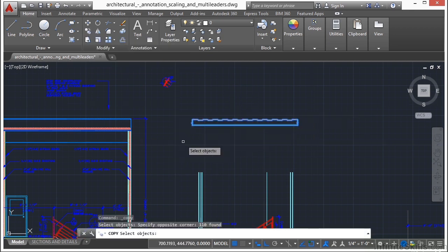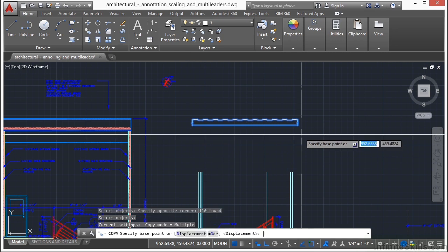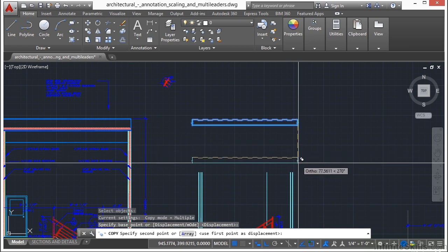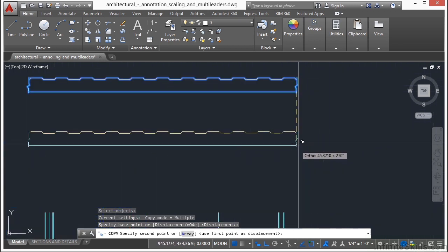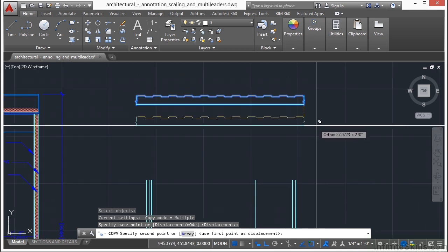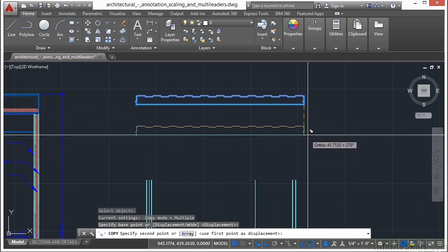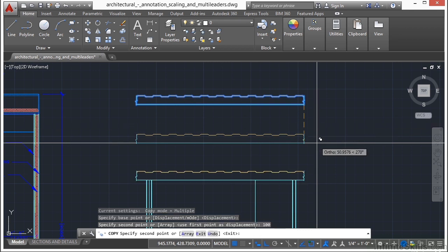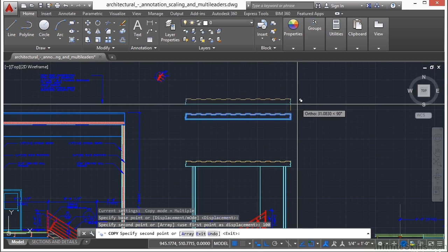Then you select your objects, just like you would in the Move command. Press Return, pick a point on there, and then move it. Now, when you execute the copy command, you can see in the top right-hand corner of my crosshairs is a little glyph. That's telling you that you're using the copy command. So if you forget what command you're in, that's there. So just like with the Move command, I can type in an absolute distance. So I want to move or copy, in this case, my roof back down 100 units. And with the copy command, you can see here that I can